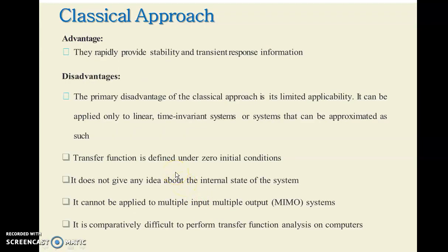The advantage of the classical approach is that it provides stability and transient response very fast, whereas it has several disadvantages also. It can only be applied to linear and time invariant systems. It does not account for any initial conditions. We don't get any idea about the internal state of the system. It cannot be applied to multiple input and multiple output systems. And it's very difficult to use the classical approach with computers.